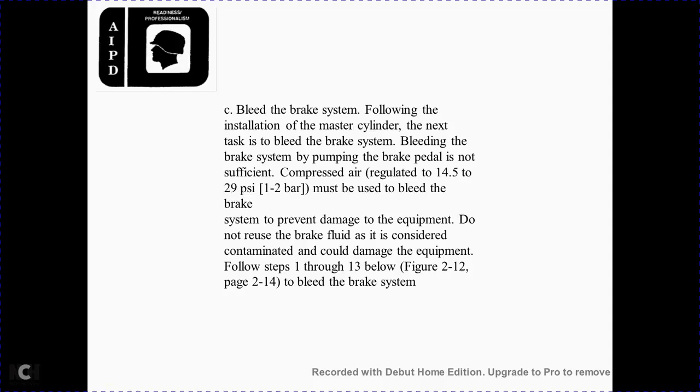Bleeding of the brake system following the installation of the master cylinder. To bleed the brake system, pump the brake pedal with sufficient compressed air regulated at 14.5 to 29 psi. Do not reuse the brake fluid, to prevent damage to the equipment. Follow steps 1 through 13 below, figure 212, and page 214 of the brake bleed system.